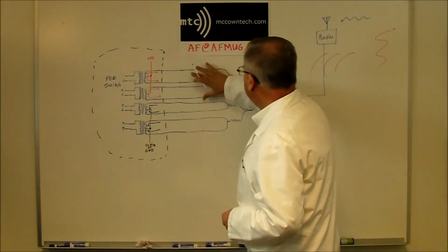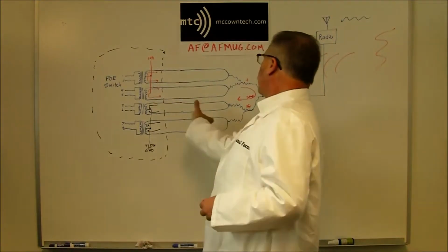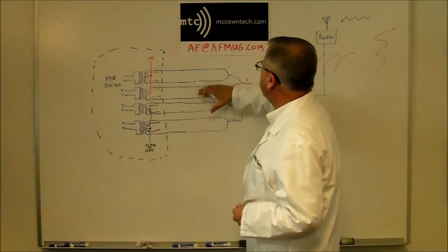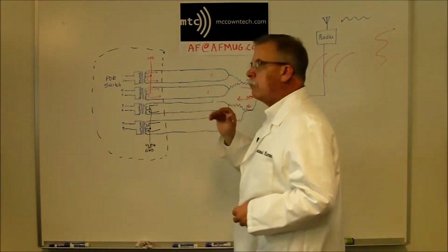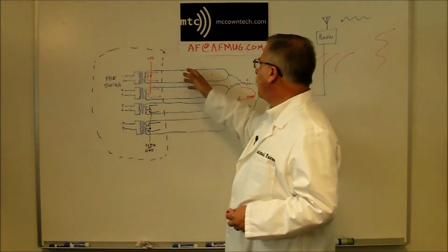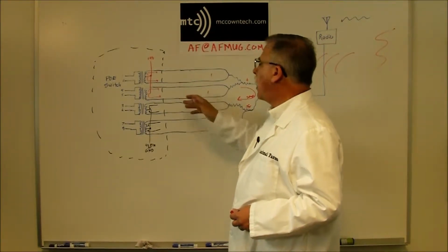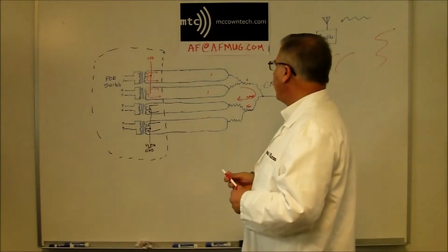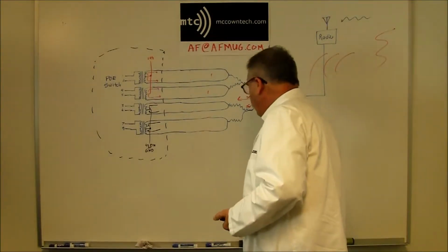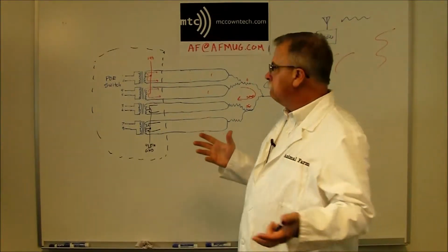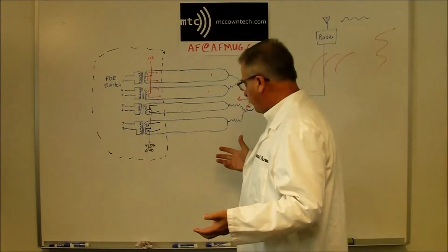So it's running on 4 wires here, and it's going out and it's coming back on 4 wires here. So you got 2 amps on 4 wires. There's 1 amp per pair. It's a half an amp per wire. Okay, half an amp per wire. Also, what do we do to limit it so that it's never more than half an amp per wire?